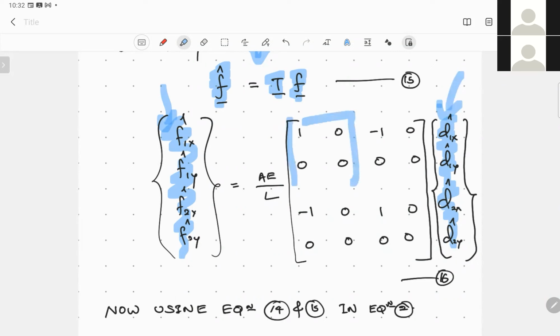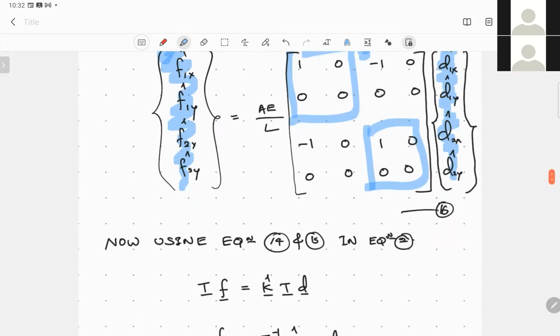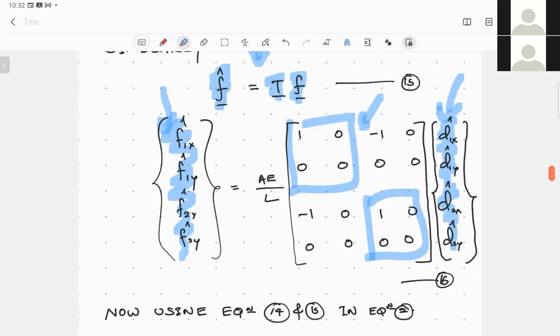We have expanded them so that the stiffness matrix becomes a square matrix, expressed for a bar element in the local coordinate system. It is the same equations that we used previously. What I have done here is simply expand them to the total nodal degrees of freedom, because we are planning to construct the global stiffness matrix equation.